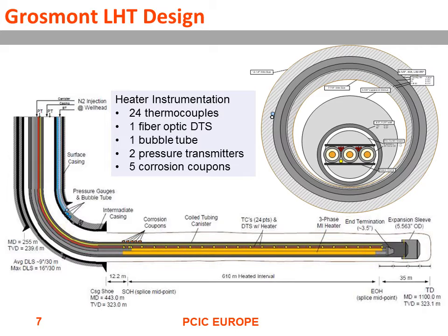If you look at the top right cross section, you can see that the 3-phase heater is there. You have the 3 phases. At the end, they're connected together in what's called a Y connection, WYE, which makes the integrity of the system a lot better, and also gives you some electrical characteristics which are very good. You can see that the heaters are there on a little platform, and that was put together so that it could be inserted into the 4.5-inch coil tube for deployment.